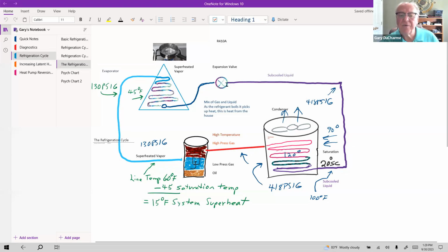Okay, this liquid refrigerant is what we need at the expansion valve. I won't even say valve, the expansion device. We need liquid refrigerant there to feed the evaporator properly. So that's the way the refrigerant is designed to work.